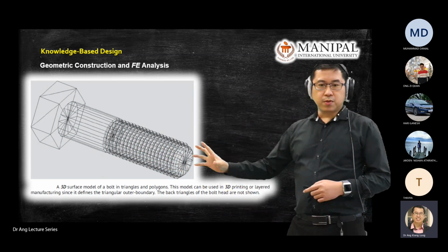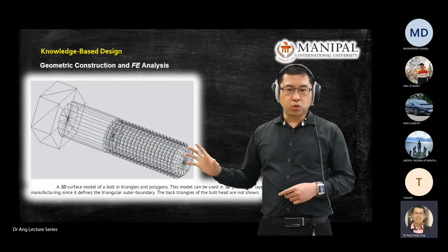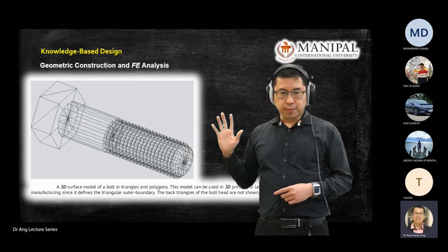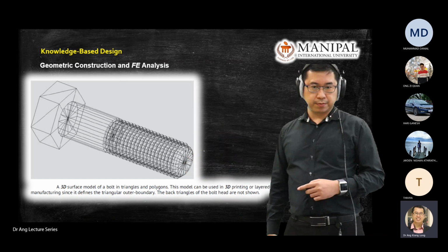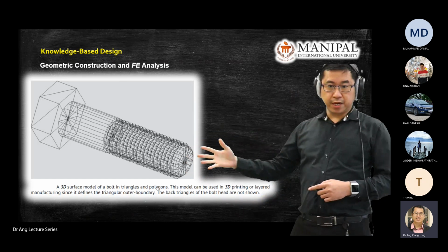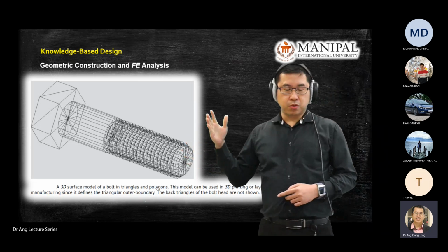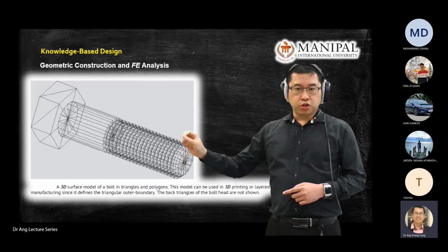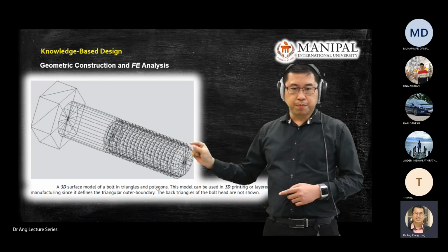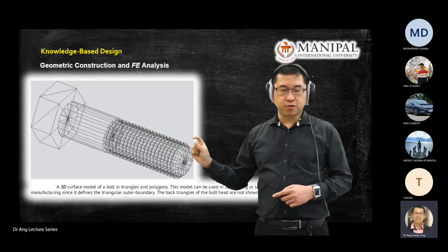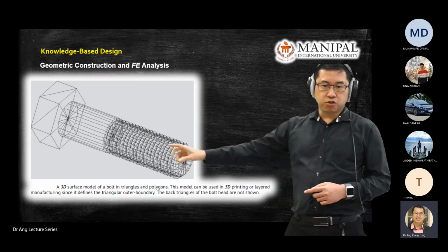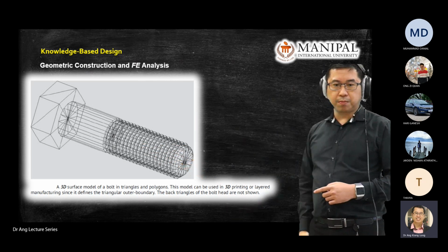Okay, so you see this when you come into optimization and also when you do finite element analysis. You will do meshing. I believe you learned what finite element analysis is before. So you need to do meshing, changing all the parts or dimensions into small pieces of rectangular, triangular or tetrahedron shape, and then you calculate the stress on the component.